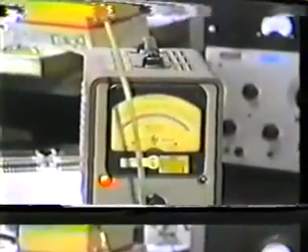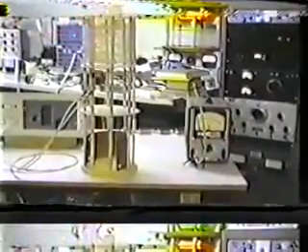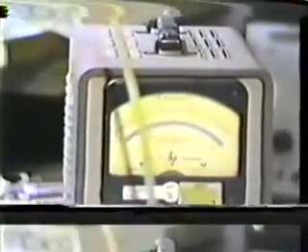So if you try to get in there to measure it, you can see by me bringing my hand near the coil that a definite shift out of resonance occurs in the meter. As an example, I'll keep my hand very close to the coil and find the new resonance peak, and it's gone down about 30 kilocycles just by bringing my hand within 3 inches of the coil. And of course, I bring it away, I have to rehunt for the new resonant frequency.